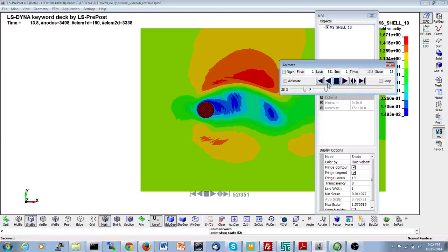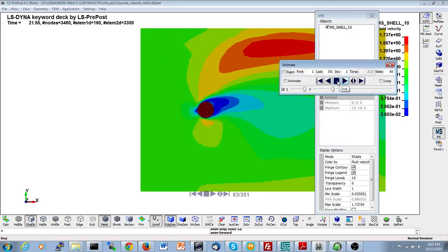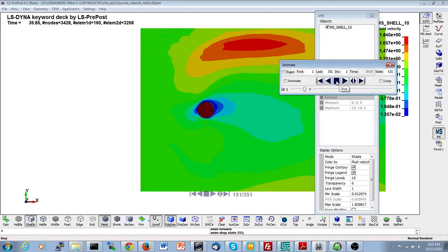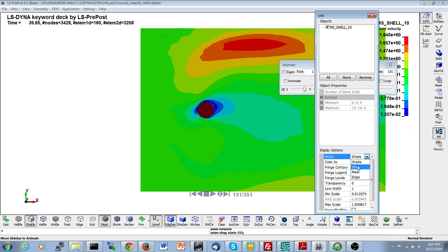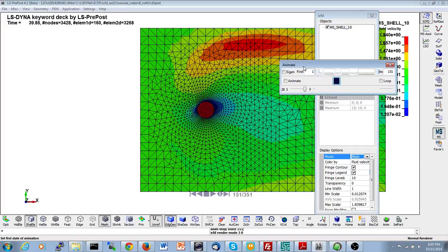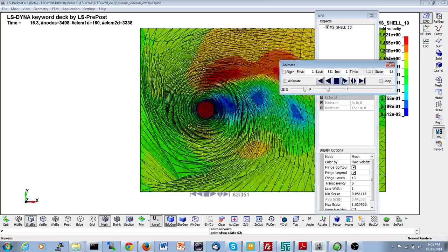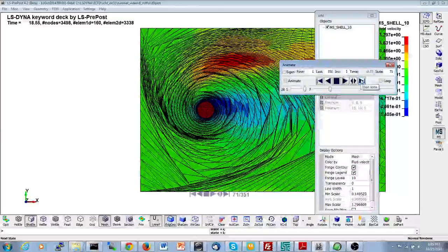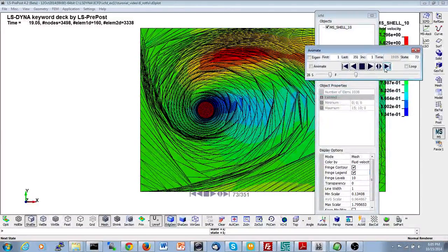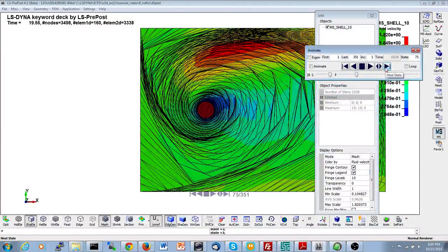If you look at it, you can see here the very strong mesh effects. But nonetheless, it's interesting to see that the solver can handle this. So by default, what's the criteria? When does the solver apply this remeshing? So the solver by default will only remesh if an element gets inverted. So you can see here that the deformation that the solver can tolerate before applying a remeshing can be pretty high. Okay, which is good, because remeshing is not something that you want to happen too often